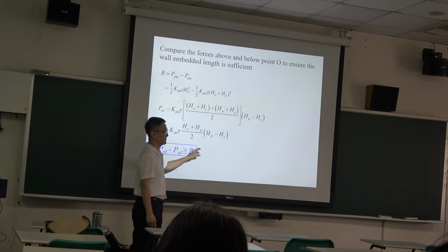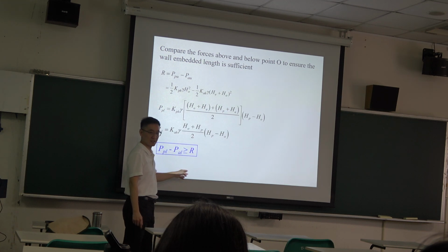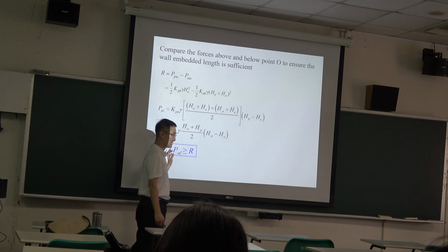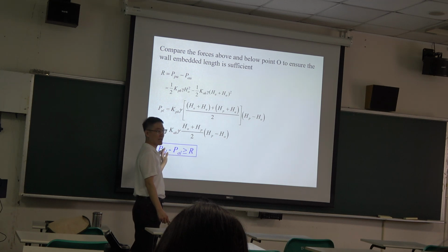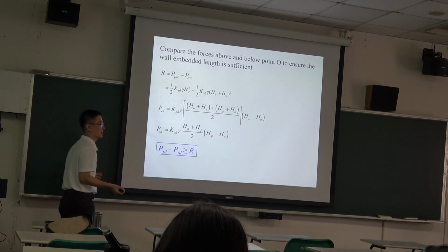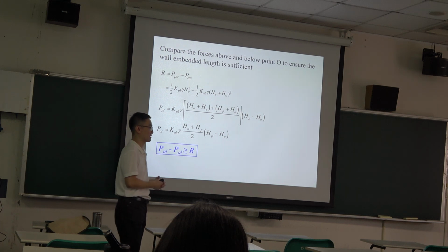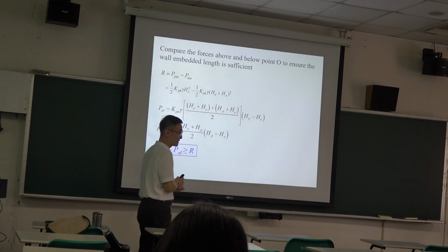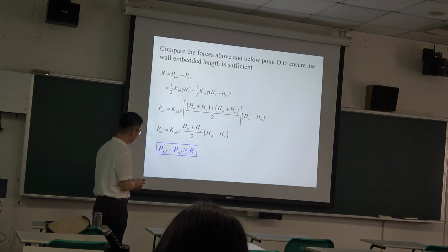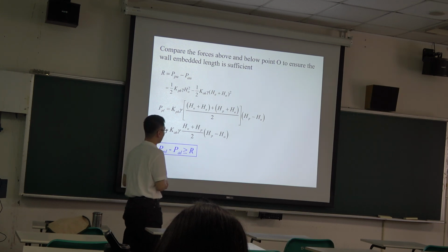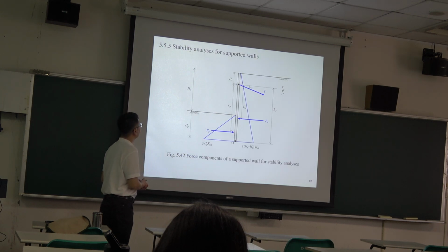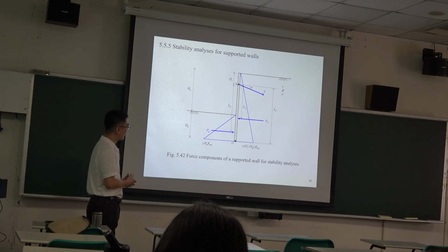If this is satisfied, it is a safe design. If not, our penetrating depth may not be sufficient, or the stiffness is not sufficient, so we have to improve our design. So that's the cantilever wall analysis.